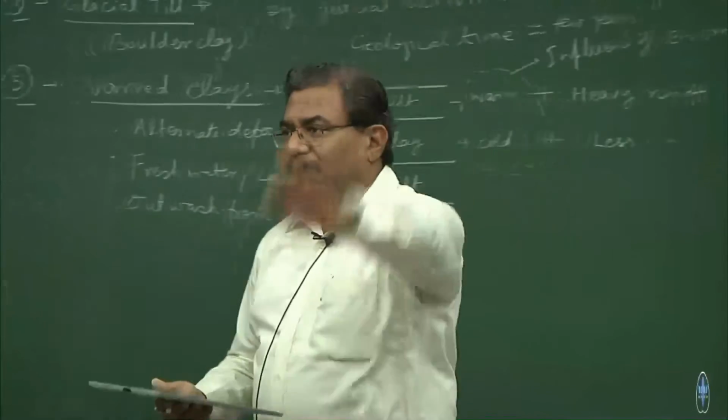Is this okay? As far as engineering is concerned, these type of deposits are a real challenge to handle. Why? Because they are extremely compressible. These are extremely compressible materials. So, no wonder when you hear of some of the buildings settling down, the first floor, second floor going inside the ground floor.